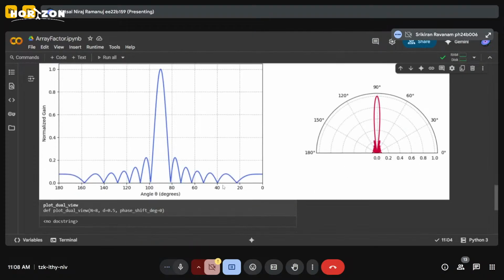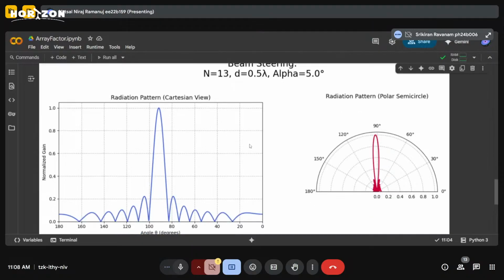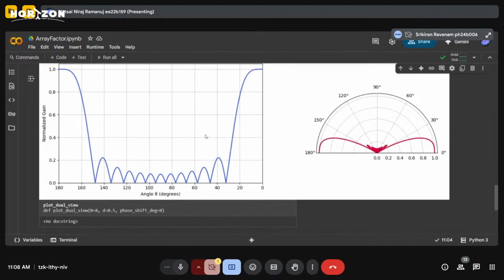So in this left-hand side graph, you can see that there are a few more lobes coming in. These are called side lobes, as they are beside the main lobe, the main gain pattern of the antenna. These are also places from which radiation can be received, but they are usually very low in power, and in antenna arrays they don't play such a huge role unless we are working with some very weird angles and they come up like this.